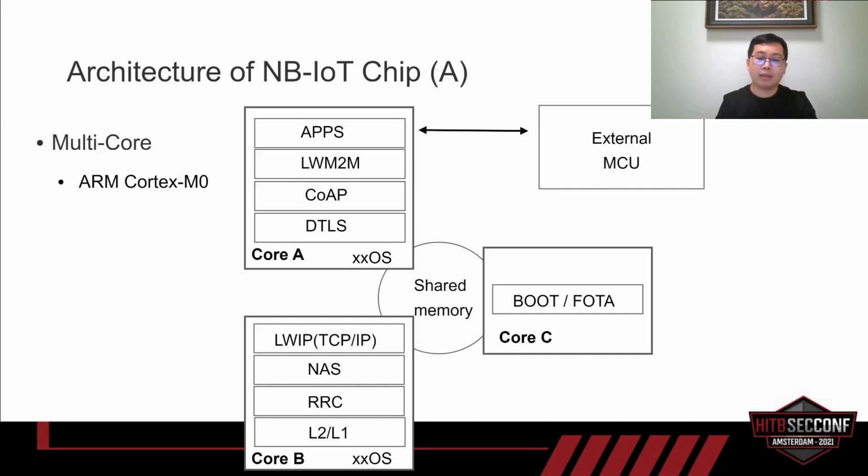In addition, it also includes the application layer, which is used to provide module vendors and developers the corresponding libraries of application development. Apps can only provide an AT command interface so that an external MCU can interact with the NB-IoT chip of modules directly through AT commands. In this way, the development of the application is mainly focused on the external MCU.